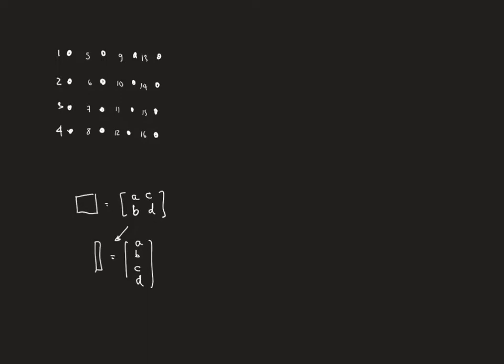Then we have to recognize something in here. These nodes are going to be the ones where the boundary conditions are imposed. These nodes here are the inner nodes, okay? So in this sense, the heat equation is going to be applied to the inner nodes and the boundary conditions to the boundary nodes. The first thing we will have to do is this transformation, okay? I will just do it.